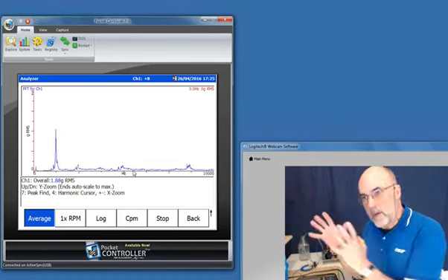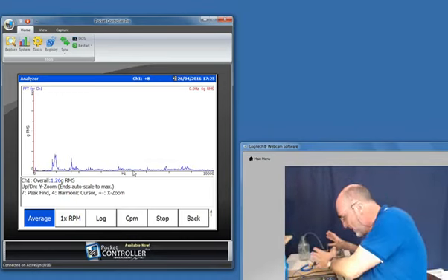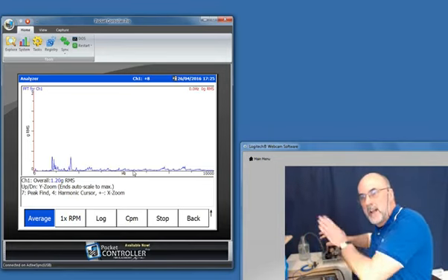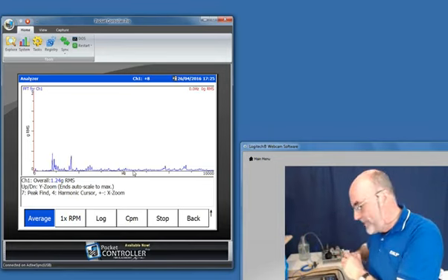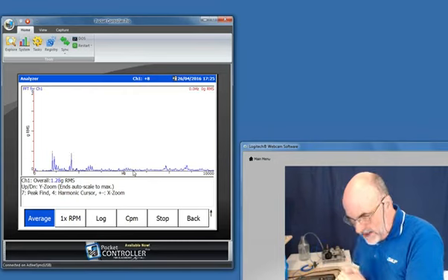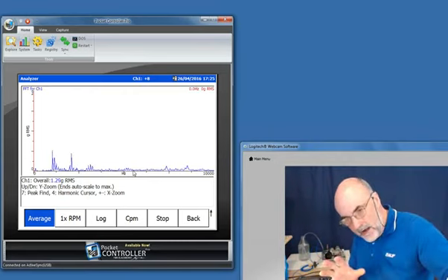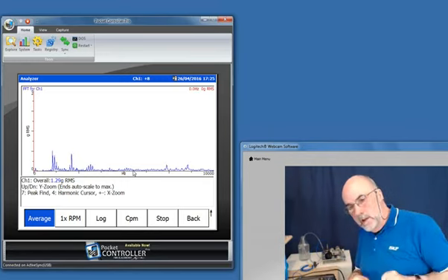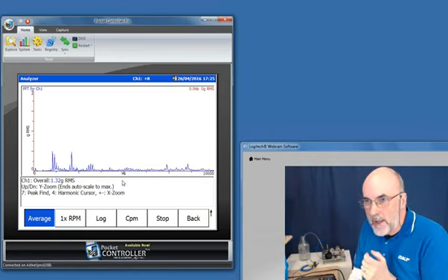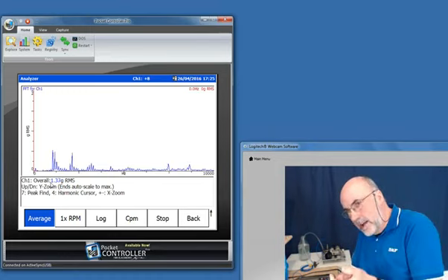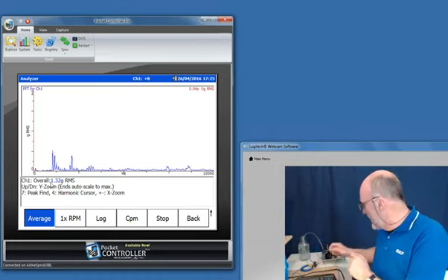So straight away, without taking my hands off the machine and on the controls of my analyzer, I can change things on the machine and look at what it does for the spectrum. I've used this on testing gas turbines. So I used to test gas turbines in aircraft, and you could go to an engine setting, write down the overall acceleration level, go to the next engine setting, write down the level, without ever touching your analyzer.